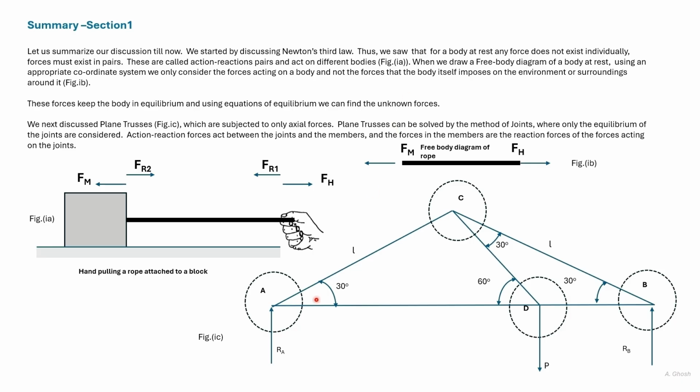Due to action-reaction pairs, the joint A will cause equal and opposite force in AC and AD. So in this manner, we get the forces in the members.